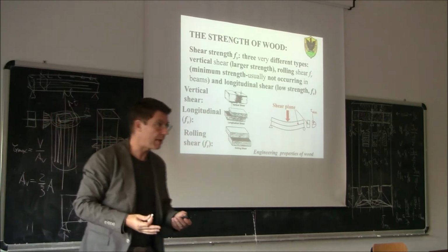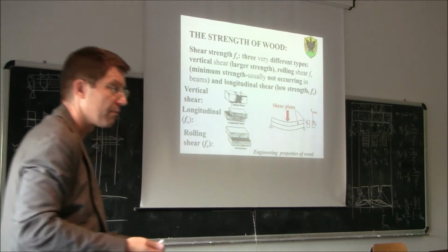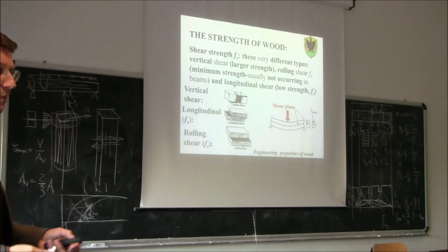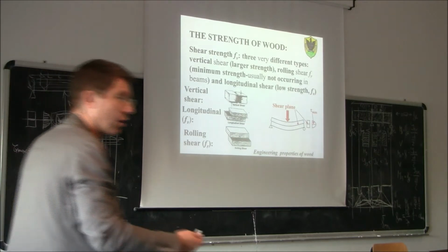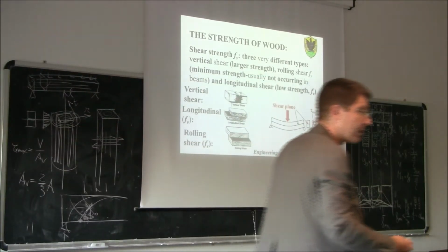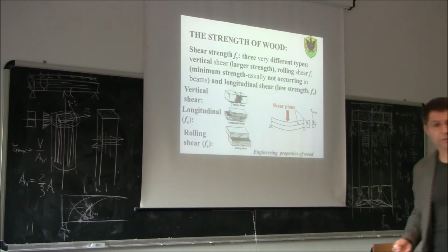So this shear plane would have to intersect the fibers and basically break them. Is it easy to break the fibers? No, because as we said before, the fibers are very strong. What is easier to break? The matrix. What is the orientation of the matrix in this case?